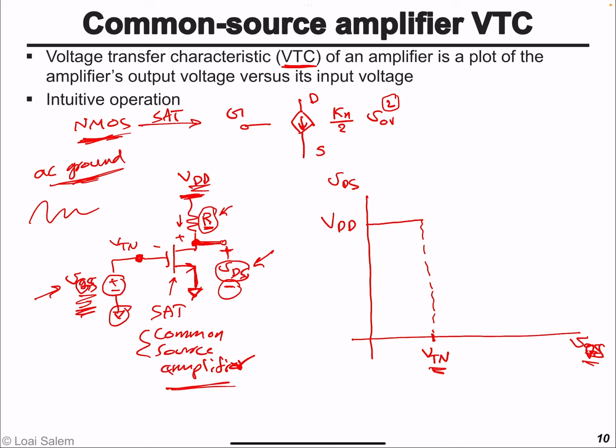So once the transistor enters the saturation, the current in the transistor essentially, as we increase VGS, will increase rapidly. And what we are going to see, since the current increases quadratically, we'll find that the voltage drop across this resistor will increase quadratically. And so essentially the output voltage is going to decrease quadratically